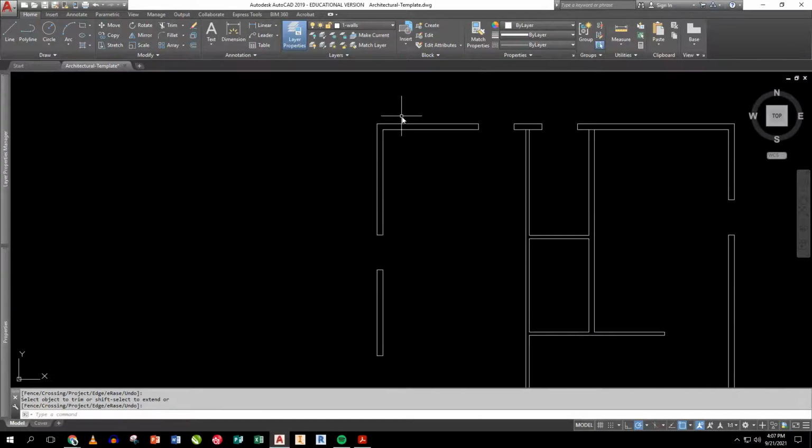From the back edge outside of the house here, offset, I'm going to go down 13 foot 6 inches. So 13 feet 6. Okay. Whoops, I did that wrong. Offset 13 feet 6 inches, enter, from here down. Now I'm going to put a partition wall right there, so I'm going to go offset 3.5 right here. Now that's the bedroom in this area.